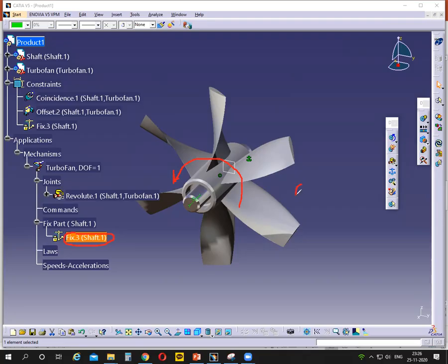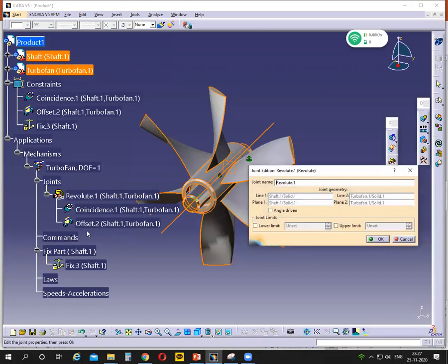angular duration, like 0 to 360 degrees, or how much angle it has to rotate, or minus 360. So 0 to 360 means here like this one. So minus 360 to 0 means in the reverse direction, okay? You can specify that one. Or minus 360 to 360 means it can rotate in both directions, okay? So where to specify? We can specify that angular duration while defining this revolute joint, or you can also specify later, okay? Later, okay.